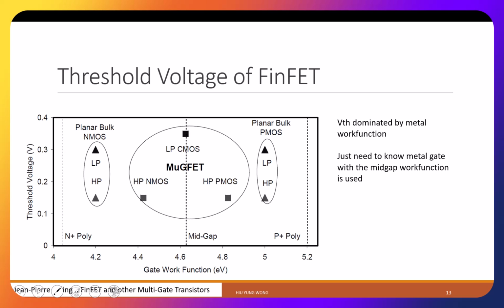So actually, it sounds to me like doping and epitaxy are two different processes. I mean, at the end of the day, they're doing maybe the same thing. You're implanting something. Yeah. But no, I don't want to distinguish doping and epitaxy. I would distinguish epitaxy and implantation, right? You can grow it while you incorporate those dopants, or you can grow the base material, and then you do the implantation and anneal it. Okay.